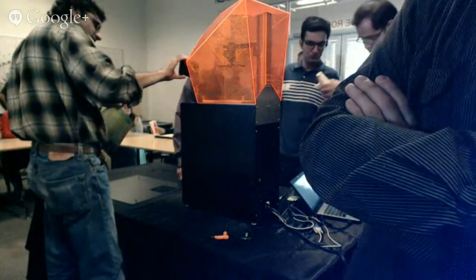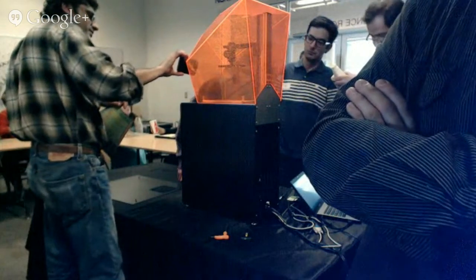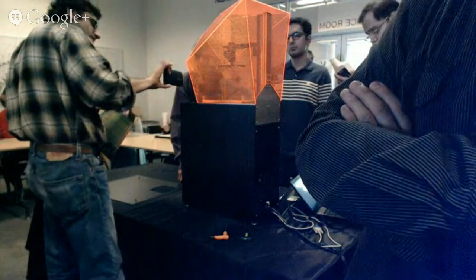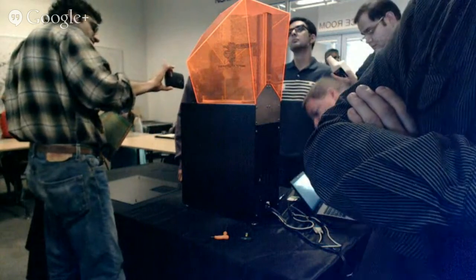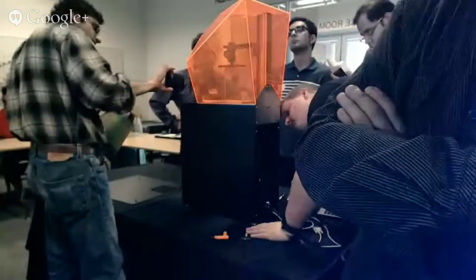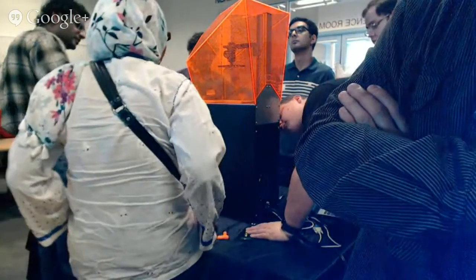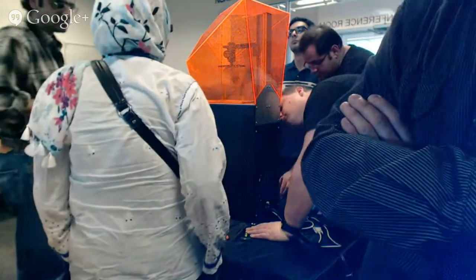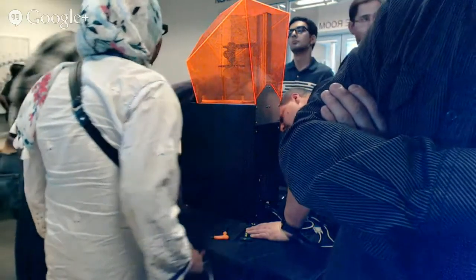Other things are the silicone over time will get roughened up. No, sorry, the Teflon will get roughened up. And as the Teflon gets roughened up, it will stick more and more. That's where the vat construction also matters, because resin is really reactive.